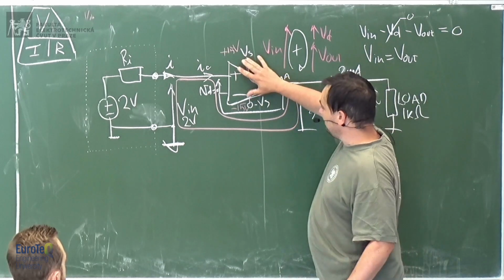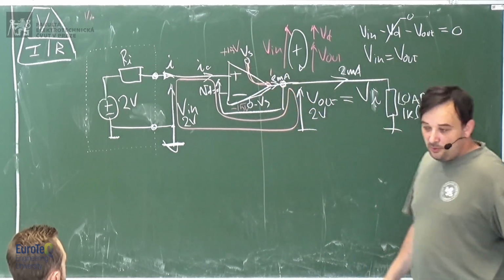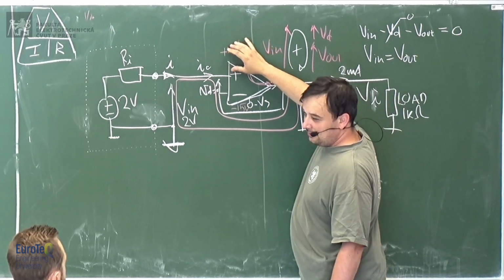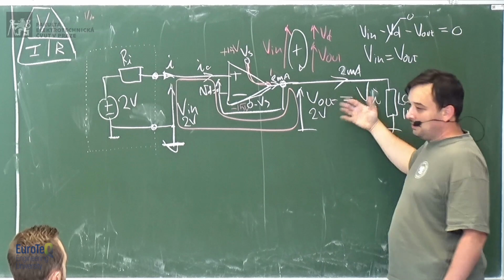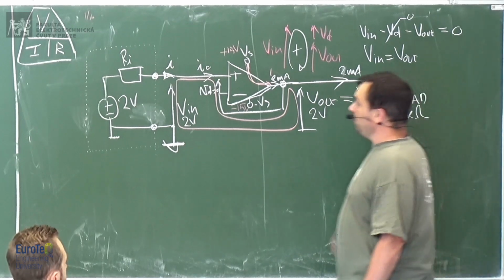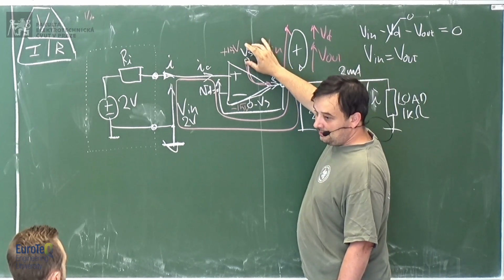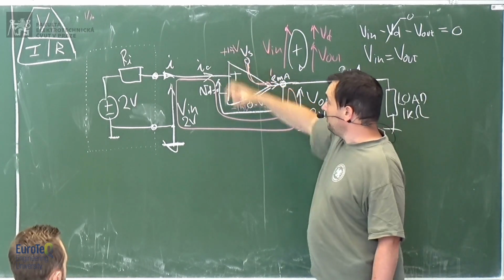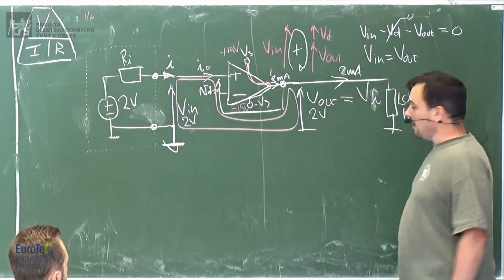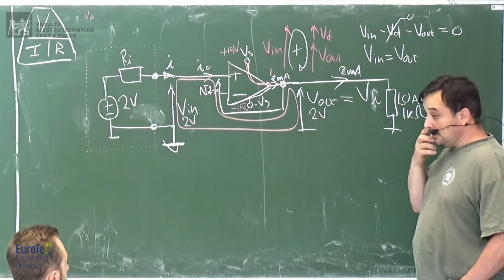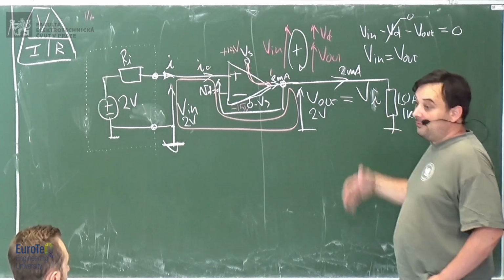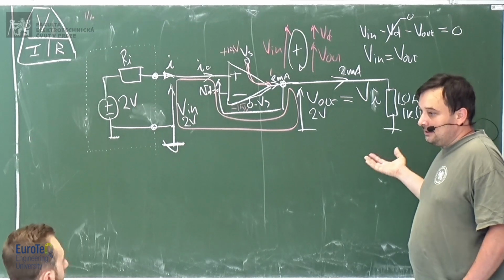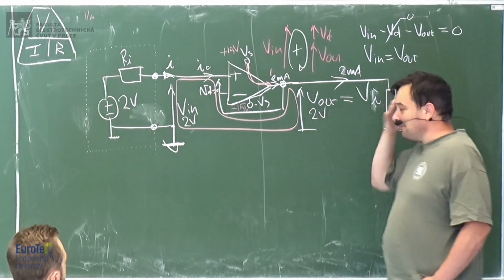Now, it's true that, generally speaking, you cannot reach directly this voltage terminal. So the maximum voltage that you can have at the output will be Vs, or minus Vs if it's a negative voltage. So if you have here 15 volts and minus 15 volts, the output could be plus minus 15 volts. It cannot produce 30 volts, 20 volts, because where does it get it from? Yeah, there needs to be a source somewhere.